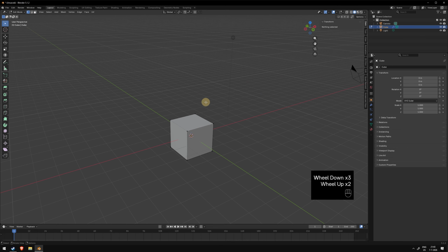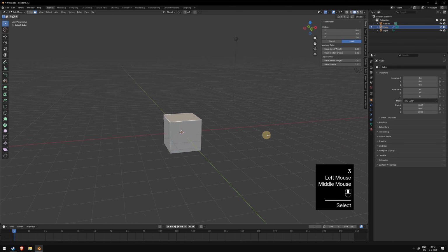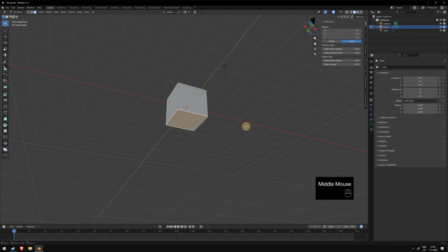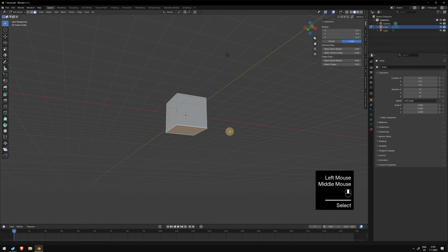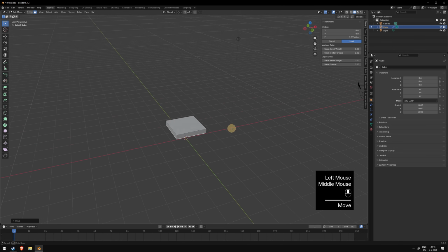I'm going to turn the default cube into a chair. I think that will be useful for explaining the shortcuts that we'll need along the way. So in order to move this bottom face up, we can select it by first pressing 3 to go into face selection mode, then left clicking the face and pressing G, which will now indicate that we have grabbed this face. If you then press Z, we will lock the axis in the Z direction, and now we can slide this face up to create the basic seat shape.